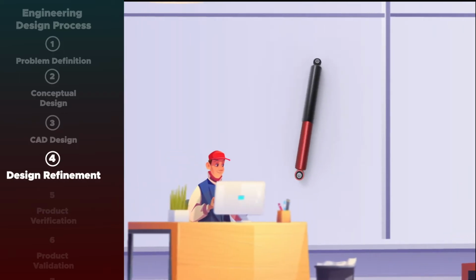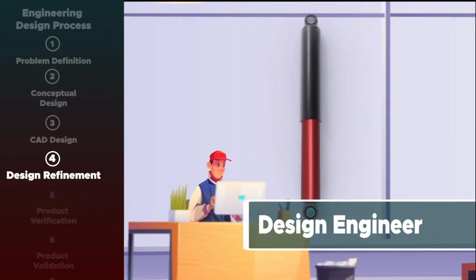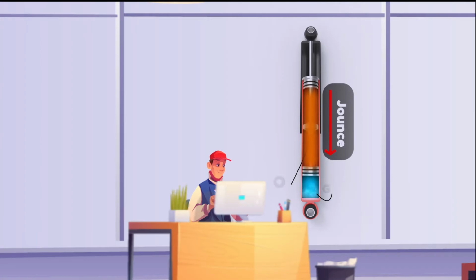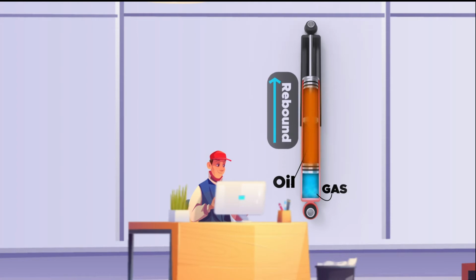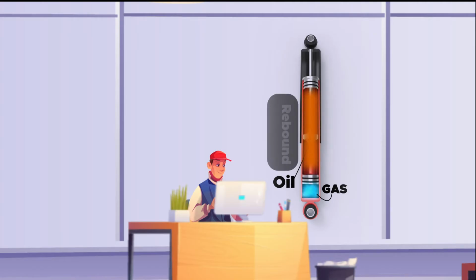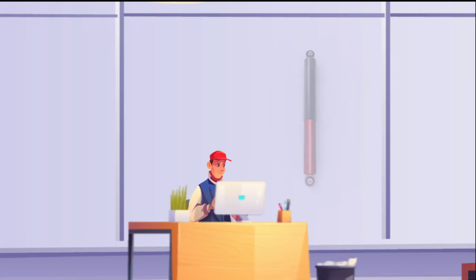During the design refinement stage of the design process, all of the individual parts arrangements, dimensions, and surface characteristics are determined by the design engineer. Additionally, the materials are specified, production possibilities are evaluated, costs are estimated, and all drawings and other production documents are created. For instance, the orifice size for the rebound valve is determined, and the material selection for the shock absorber components is defined.